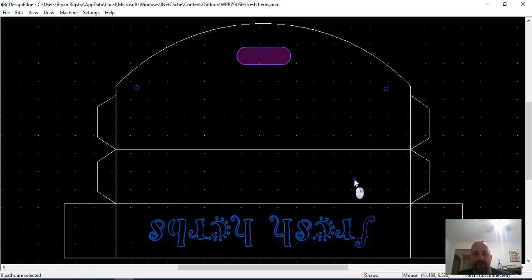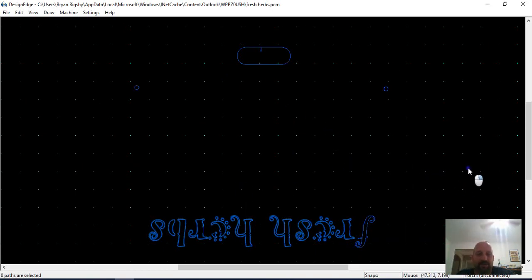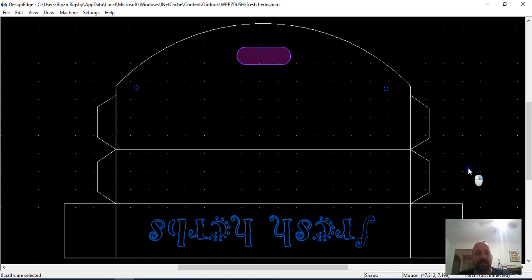If you hide with Advanced Design, F9 will hide your cut paths, and so we can see what open paths and closed paths, regular paths, we have, and then we press that again. F10 toggles off those regulars, and we see the cut paths. So at first glance, we need all regular paths.